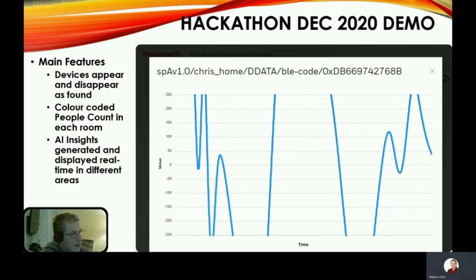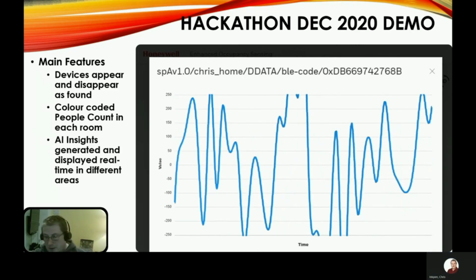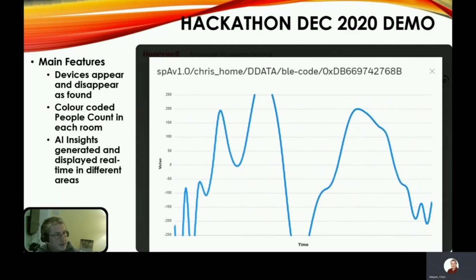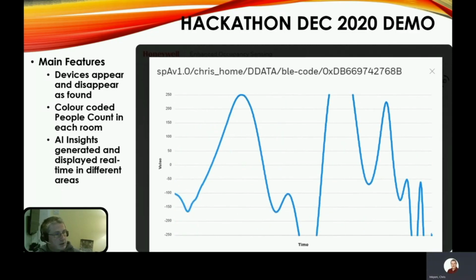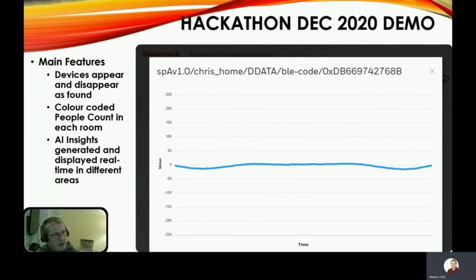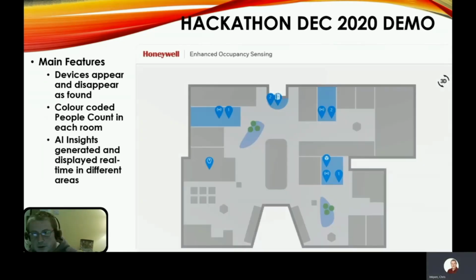So you can actually infer an awful lot of information from this signal, but really, it's an awful lot of number crunching to do that. And so we tend to use PIR sensors really to indicate there is at least one person in this building. We don't know how many, but we know there's at least one.